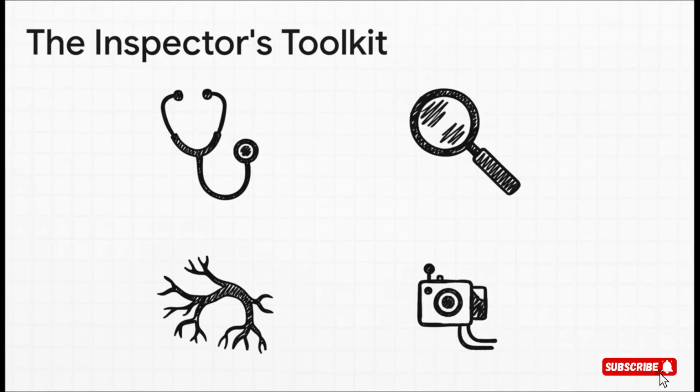So these are the big players in our toolkit for external surveys. You can kind of think of them like different tools a doctor would use. CIPS, that's your overall health checkup. DCVG and ACVG, those are like the precision scalpels for finding very specific injuries. And ACCA, well, that's for checking the pipeline's electrical circulatory system. We're going to get into each one of these.